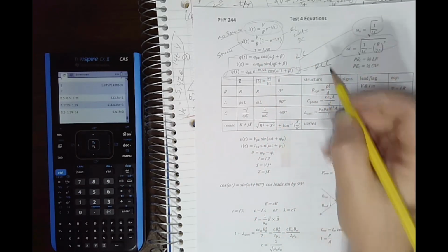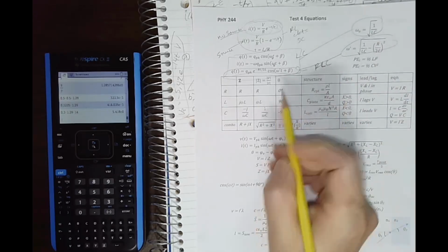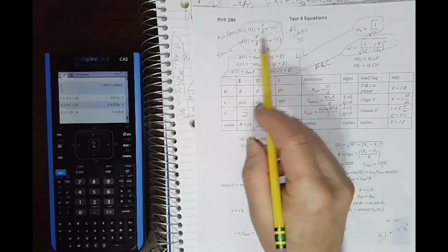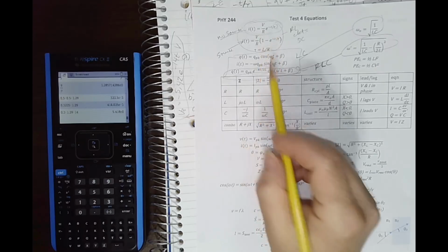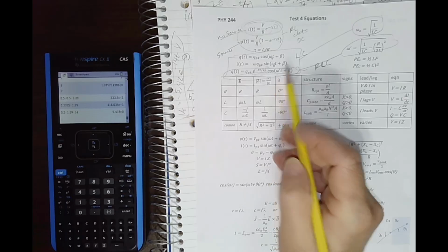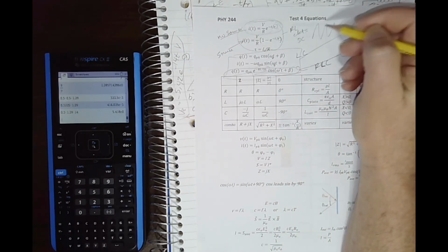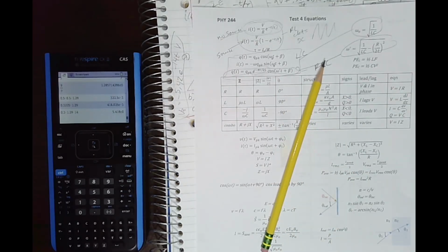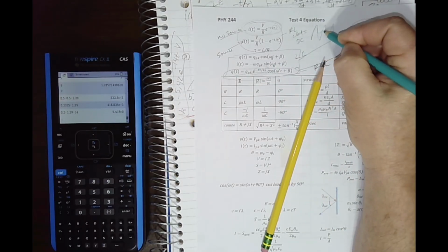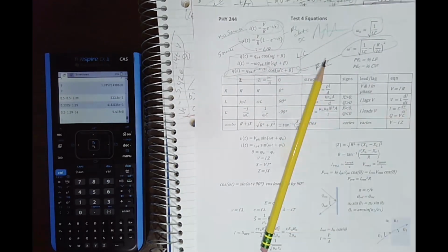When we add in a resistor, R, L, and C, now we get an exponential kind of thing like we had for the inductor and resistor circuit. And so we have a decaying cosine. So instead of just being a cosine that goes on forever, it's a cosine that is multiplied by an exponential with a negative coefficient. So it's going to come down, and eventually it's going to die out.